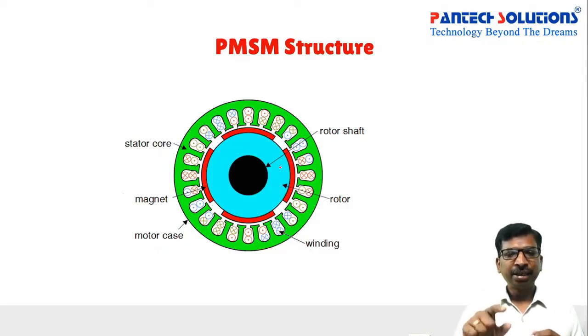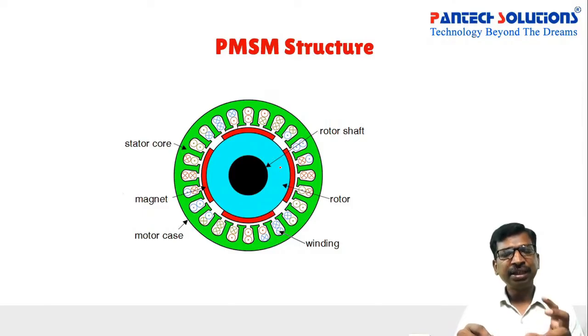Right. So inside, the rotor is a permanent magnet. Whenever a magnetic pole is generated in the stator, this rotor magnet will try to catch or align with the stator. So if you run the entire supply, the stator magnetic pole will try to revolve inside the stator. Finally the rotor will try to catch it, then follow it, and keep running continuously as per the stator magnetic pole. So this is the basic working principle, and again in detail we will discuss how it is working in the next slides.